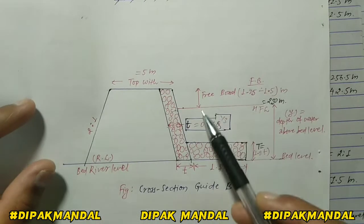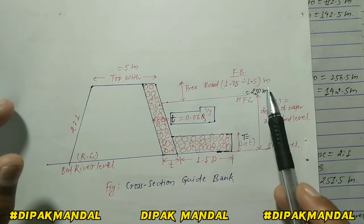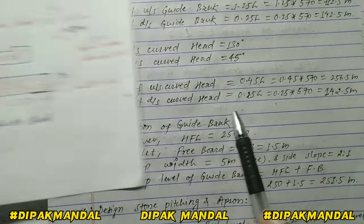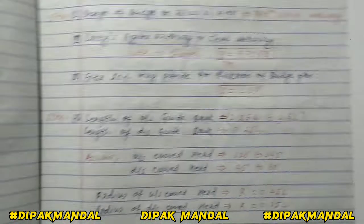This is the freeboard. We have to provide freeboard between 1.25 to 1.5 meter, as we already discussed in the design criteria. So the freeboard is taken here as 1.5 meter, and top width equal to 5 meter, as we discussed in the design criteria.